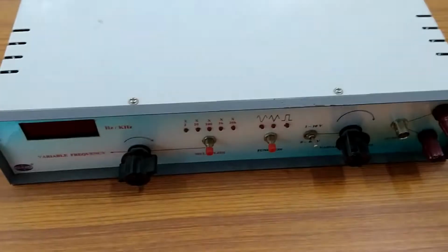And at resonance in a series circuit, the total resistance offered is minimum and it is equal to R, because in series LCR resonance at a resonant frequency FR, XL is equal to XC. XL is the inductive reactance and XC is the capacitive reactance. Since both of them are equal at the resonant frequency, in a series circuit the resistance offered by the circuit is low and hence the current is more.